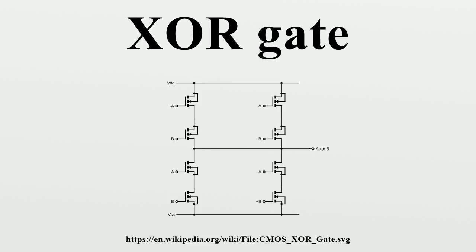The result is a circuit that outputs a 1 when the number of 1s at its inputs is odd, and a 0 when the number of incoming 1s is even. This makes it practically useful as a parity generator or a modulo 2 adder. For example, the 74LVC1G386 microchip is advertised as a 3-input logic gate, and implements a parity generator.